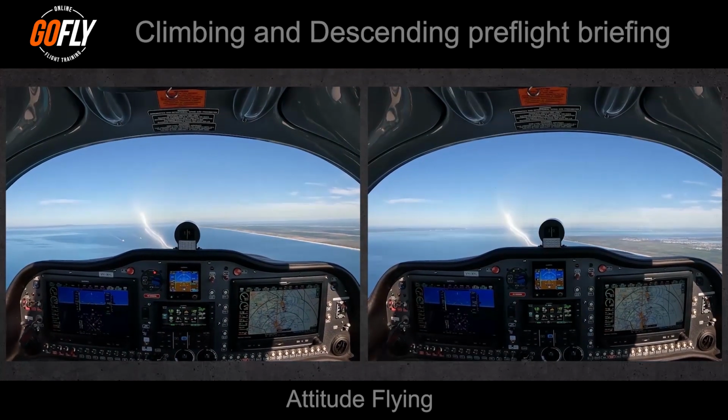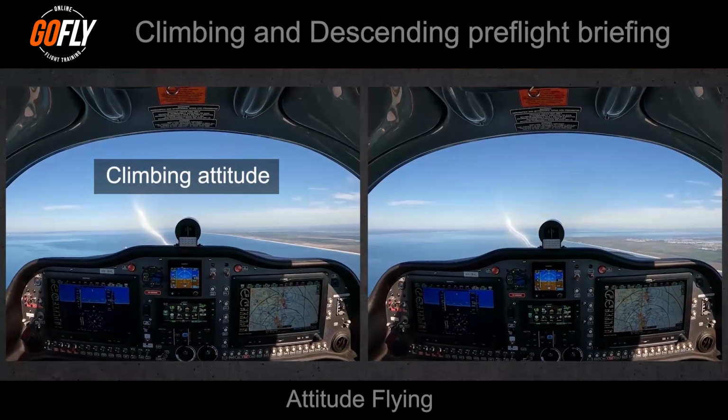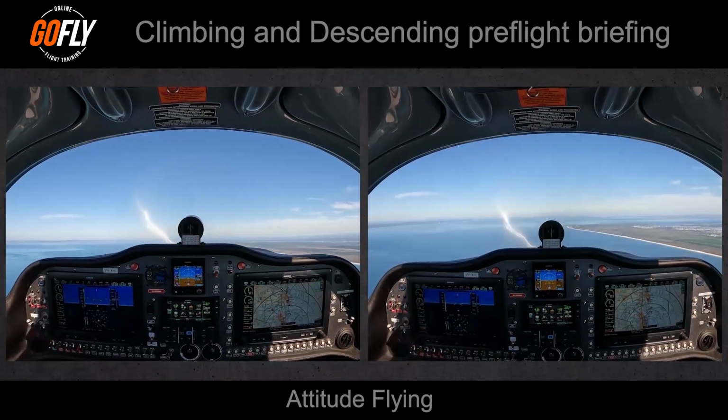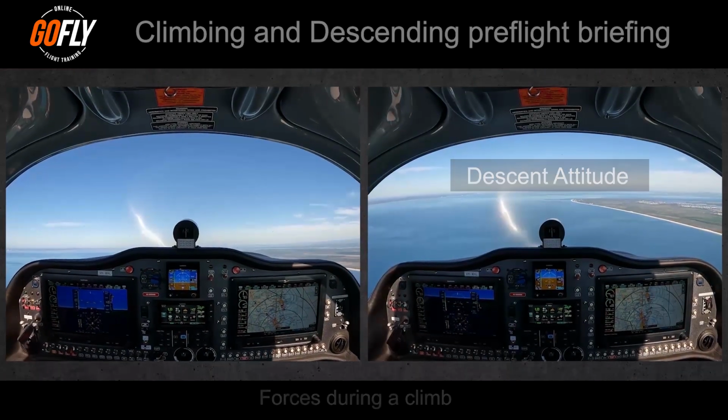As a general rule, when the aircraft enters a climb, the gap between the nose of the aircraft and the horizon gets smaller, and when the aircraft enters a descent, the gap between the nose of the aircraft and the horizon gets larger.